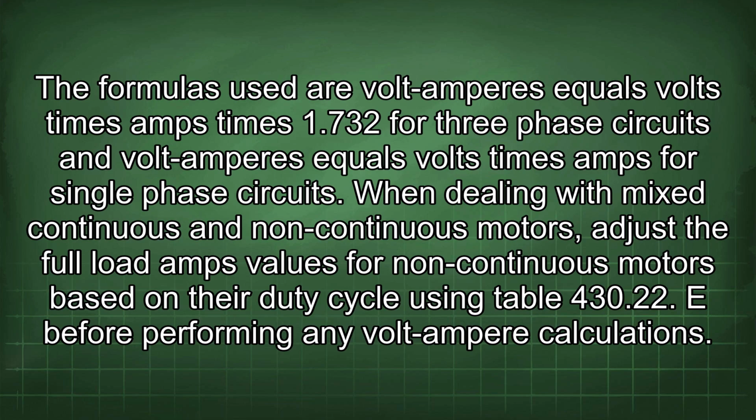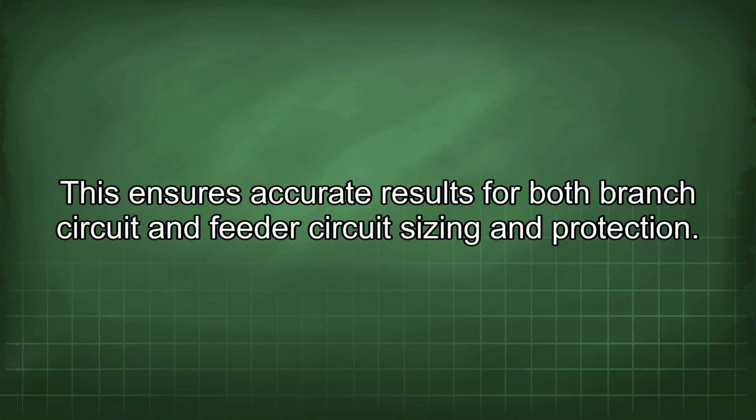When dealing with mixed continuous and non-continuous motors, adjust the full load amps values for non-continuous motors based on their duty cycle using table 430.22 before performing any volt-ampere calculations. This ensures accurate results for both branch circuits and feeder circuit sizing and protection.